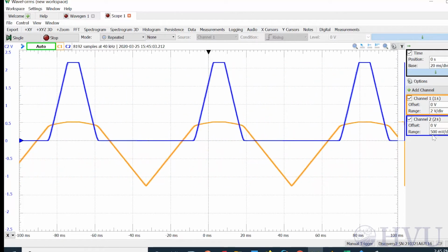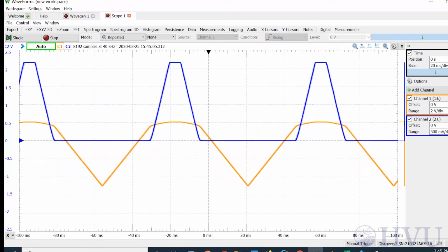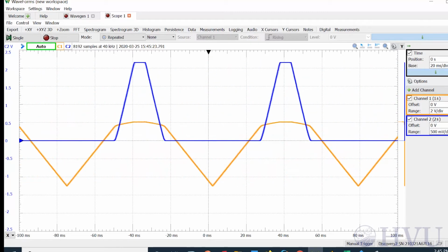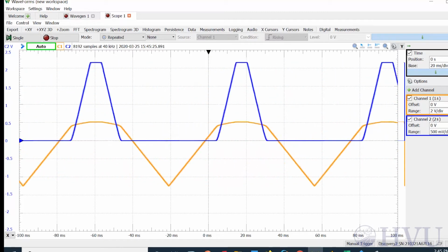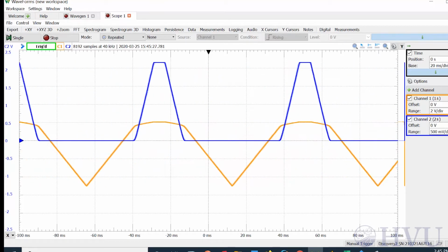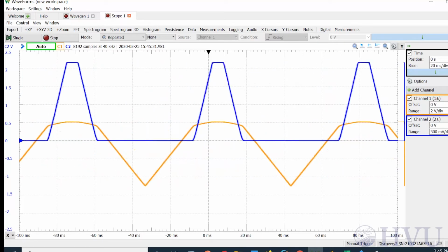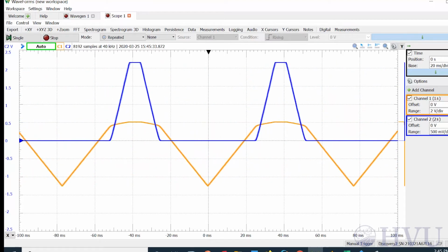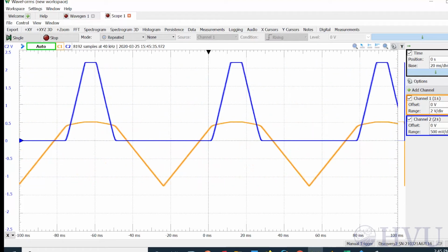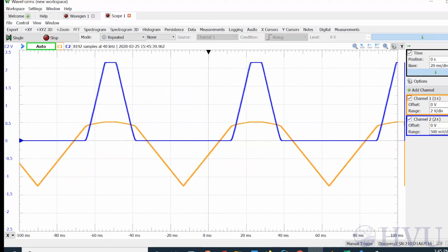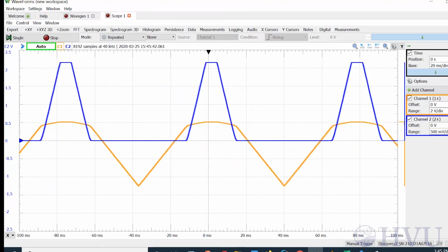Now we can see a lot of detail in our signal, but it keeps jumping around. In repeated mode, the oscilloscope displays frames of data, much in the way a movie is composed of static picture frames which are successively displayed to give the impression of movement. What we need to do is make the successive pictures coalesce to create a coherent display. On an oscilloscope, this is usually done by setting what is called a trigger.